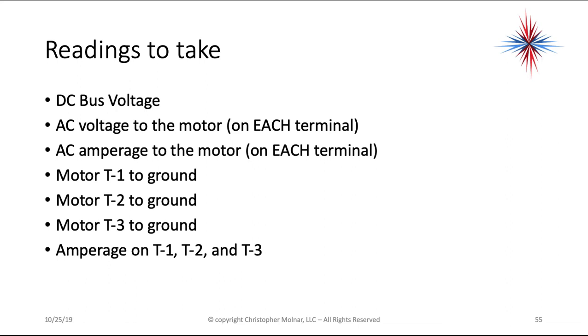Then you go AC voltage to the motor on each terminal, AC amperage to the motor on each terminal. T1 to ground, T2 to ground, T3 to ground. Amperage on T1, T2, and T3.